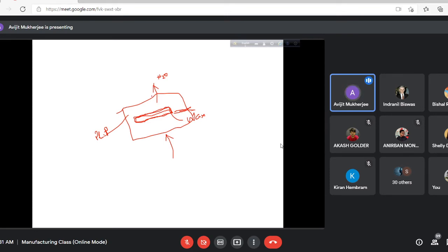Now, again, this is not as simple. You will have to provide some gate, riser, runner, all these to pour molten metal. After that, you pour molten metal, say aluminum or the exact material that is needed, maybe radioactive metal also. Fill this cavity with that material and allow it to solidify. After solidification, break the plaster of Paris mold.